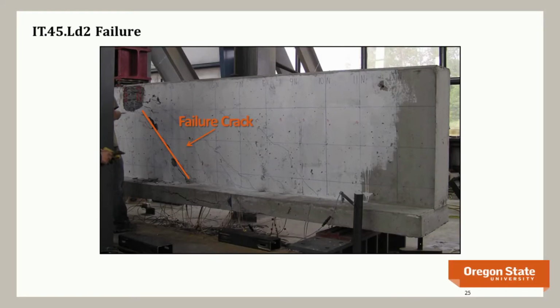So here's a flexural specimen. This is the control one. The little blue arrow, I wish I had an ability to show it to you, but on the bottom flange, about halfway over, you see a blue arrow. That's where the bar is cut off. And if you look closely at the deck, you can see that you've got splitting failure of the deck because that anchored bar was improperly anchored and essentially had a bond failure.